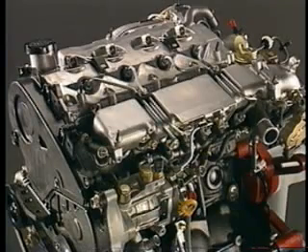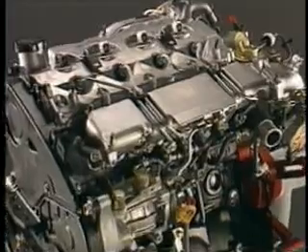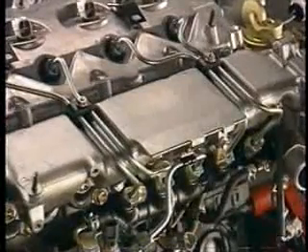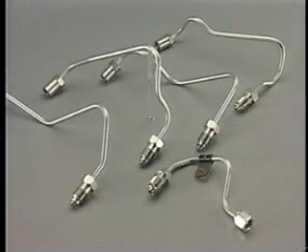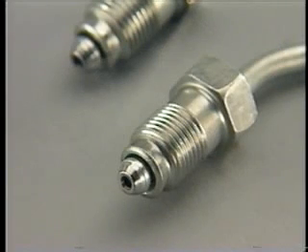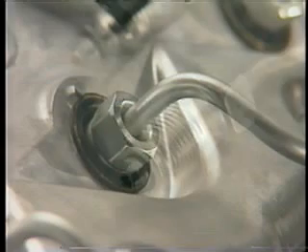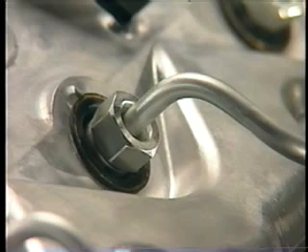The pressure of the fuel becomes extremely high in the common rail. Therefore, pay close attention when installing the unions of the injection pipes or the inlet pipes. If any operation that causes the contact of the union to change, such as the replacement of parts, is performed, make sure to replace the pipe. For details, refer to the repair manual. After tightening a union, make sure to check for leaks with the fuel pressure raised.